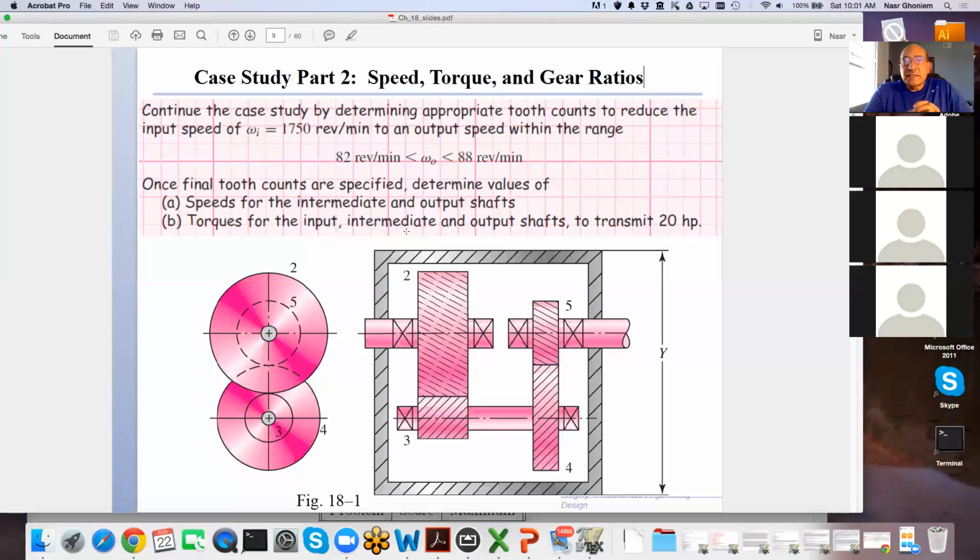If we decided that we have to have 4 gears in this case, because the reduction ratio is less than 100, then we would be able to determine the sizes from the requirement of the size of the gearbox. So this has nothing to do with the input velocity or input speed or the input horsepower.